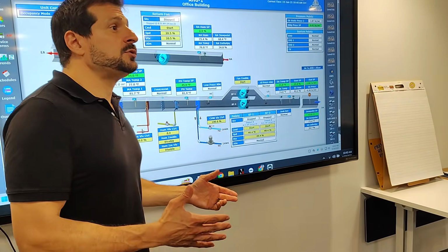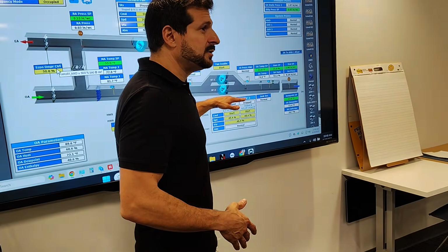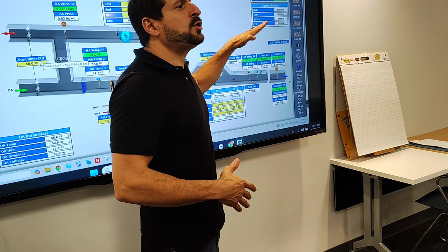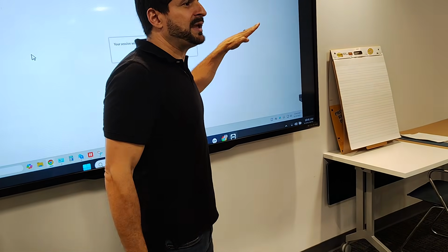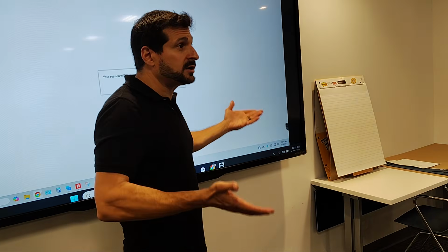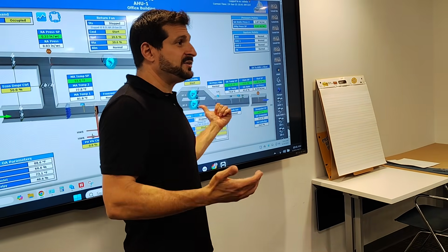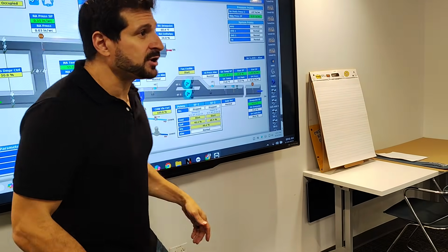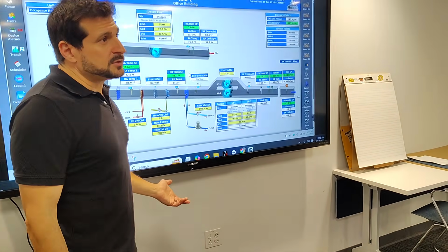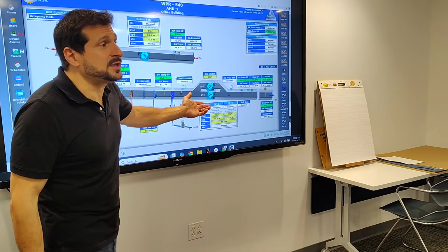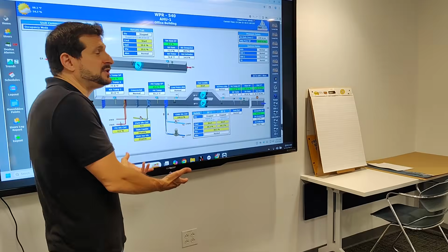Well, no. Let's say this thing ramps up, gets all the way to 90%, and we're at 2 inches of pressure. Then all of a sudden a fire damper closes on a main trunk. When that fire damper closes, the pressure in the duct is going to rise. Is the VFD going to take another 30 minutes to slow down? Because if it is, then you have other problems. You're going to be reliant upon your high pressure limits. Maybe those are not set up right? There's a lot of stuff here that you need to think about.